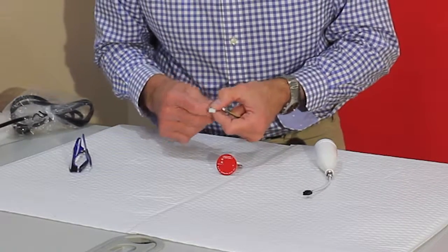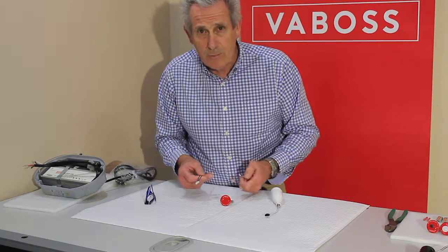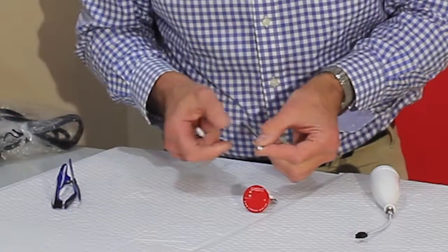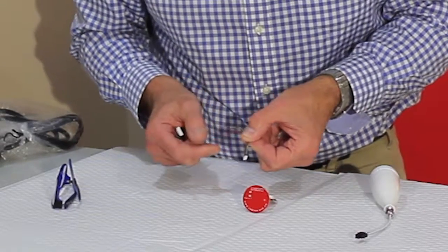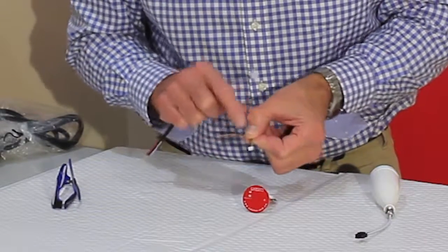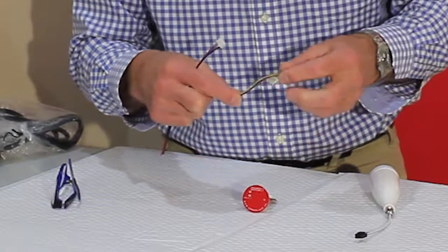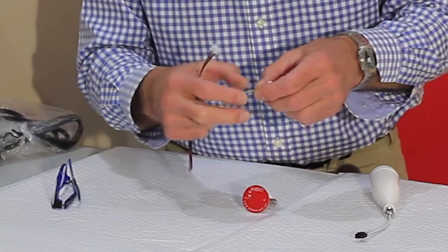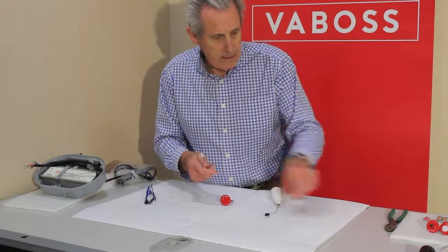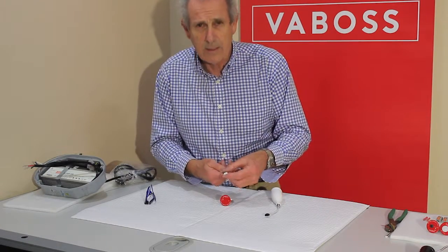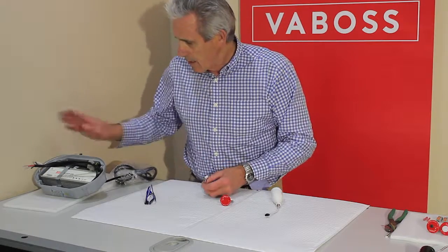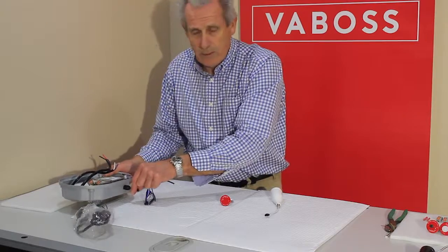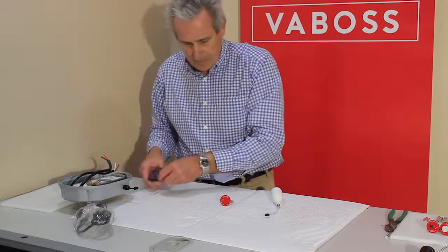One is a micro XH 2.54, which is this big one here, and there's a smaller one. It's a pico blade, it's half the size, and pico blade needs really fine cable. It's 28 AWG, it's very fine. In this instance, we'll leave that aside. In this instance we're using the micro, and we have one already installed in here, which we'll look at.